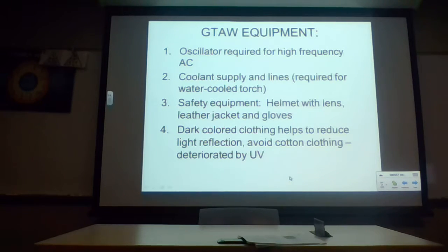Also, there's some very nice equipment out there that will produce a square wave, where we can alter the sine wave that's being produced in welding, and we can control penetration. We can also control the other factors in the weld a lot better than what we could do in the past. So there's some specialty equipment out there that was really nice.